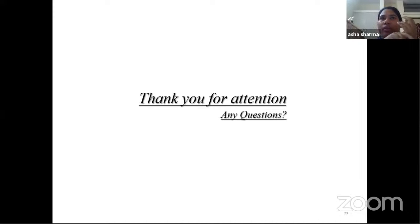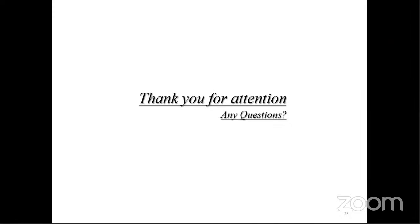As I already told, this up and down method and the extended up and down method are both called self-restoring type of insulation. That is one thing. We do all these types of testing for a large number of samples. As I have already told in my initial slides, if some of the specimens fail and some of the specimens do not fail, we need to use some type of distribution. One of the distributions that I have discussed is the Weibull distribution. And then according to that, we estimate our breakdown probability.